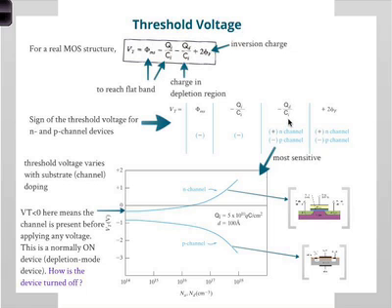But of course the depletion region for a p-type substrate is negatively charged. The acceptor ions accept the electrons, so it becomes negatively charged. But for an n-type substrate, it's positively charged, it gives away electrons, right? You have donors. So that's obvious from a p-n junction. So this is positive, that's negative. Okay, there's a negative sign there.